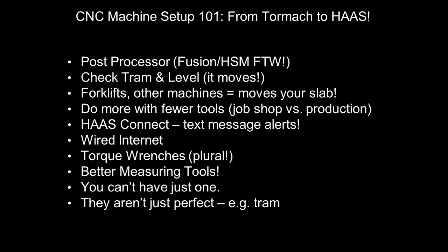It's been great for our standard 3-axis stuff, and we did get a little trunnion, which I've only played with once, and I think I had to get a slightly tweaked post because we have a weird trunnion. But basically the default post there works for 5th axis, which is something that I think costs thousands of dollars if you've got to buy normally for something bespoke.